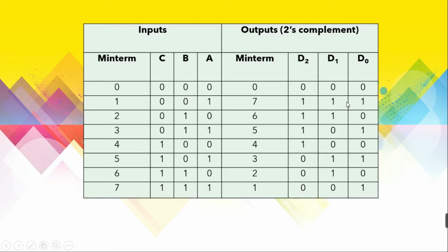All right, so this table right here just shows the actual truth table for our experiment, where we're inputting 3-bit numbers, and we intend to get the 2's complement representation for those 3-bit numbers. So this is basically the truth table. And if you want to take a look at the min terms, you will also understand how the min terms are written here.